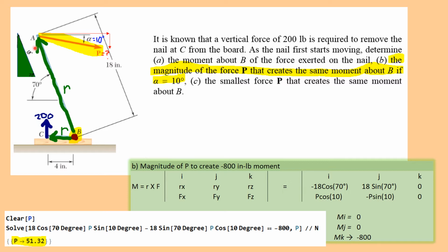And that's the point of a crowbar. That's the point of a lever arm, right? You have this nice big lever arm, and you can pull it with a very small force here. Only 50 pounds here creates big 200-pound over here. So that's nice little mechanical advantage going on right there. And you can see that advantage 4 to 8, okay? So that lever arm mechanical advantage translates into a force mechanical advantage, 50 to 200.